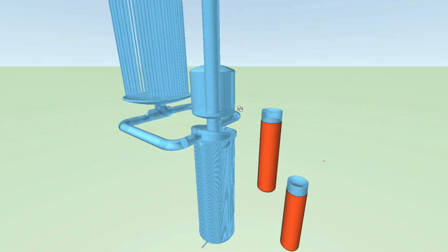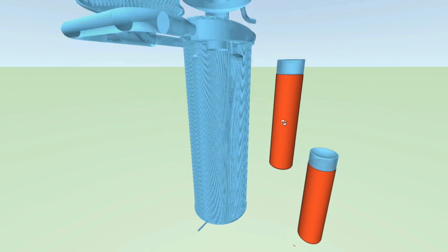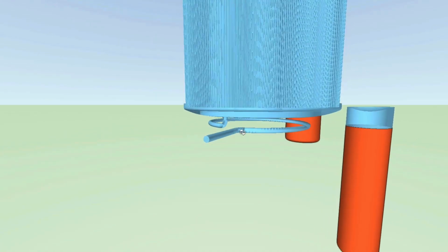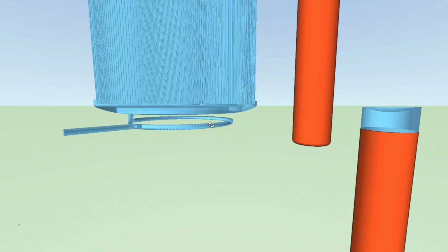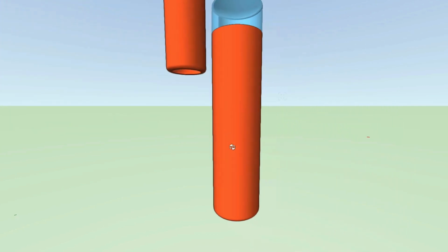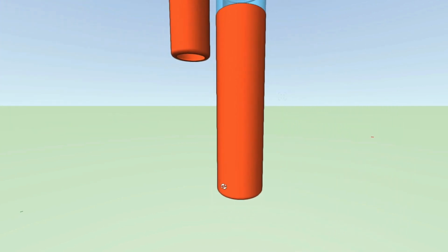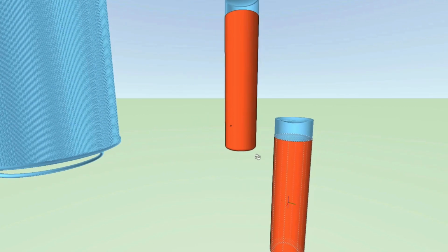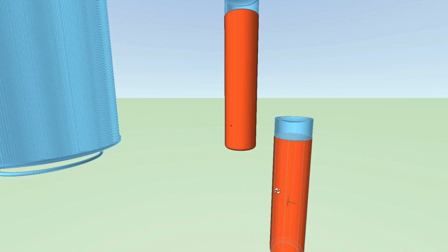Now, if they want to drain out all the fuel, the reactor fuel would already be in here once the pump is shut down. Then there's a drain pipe right here. I don't quite have it pointing in the right position, but it comes out here, goes down here, and connects into this and fills up this way. And with power loss to the site, this freeze valve thaws out and they both equalize.